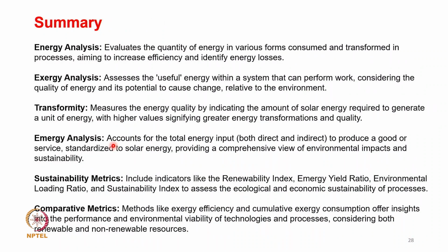Okay, so I think we are now concluding our discussion today. We will just summarize what we have learned. What is energy analysis? It evaluates the quantity of energy in various forms consumed and transformed in a process, aiming to reduce energy losses and increase efficiency. Exergy analysis assesses the useful energy within the system that can perform work, considering the quality of energy and its potential to cause a change, relative to the environment as the reference state.